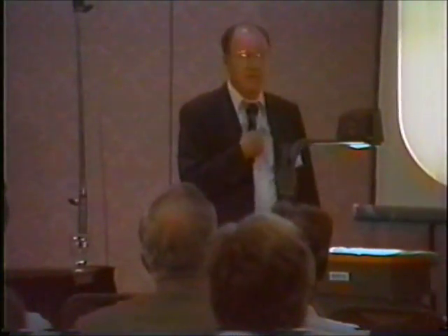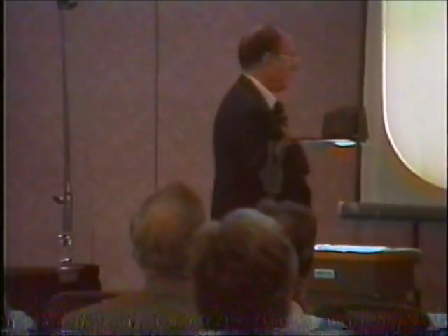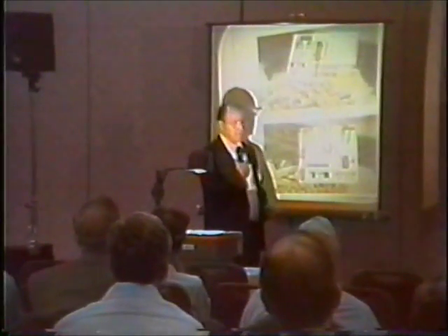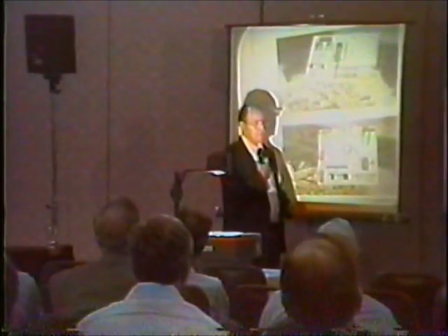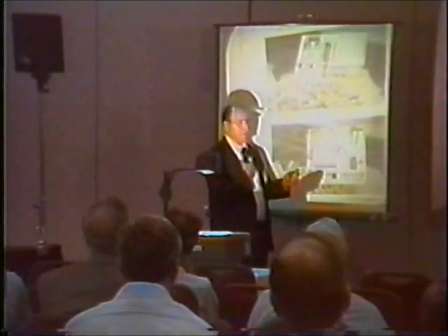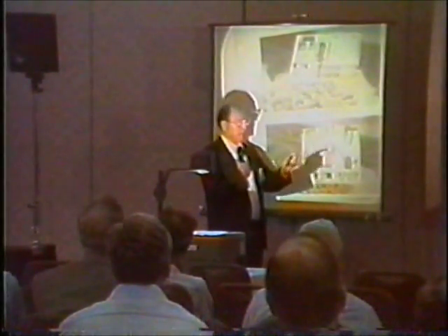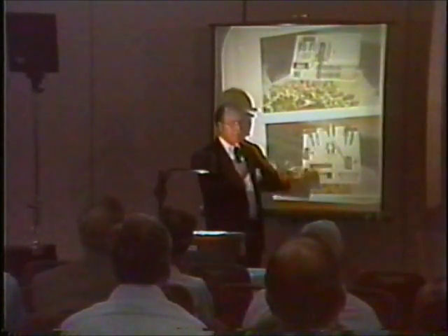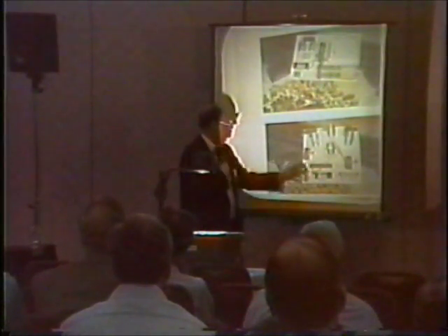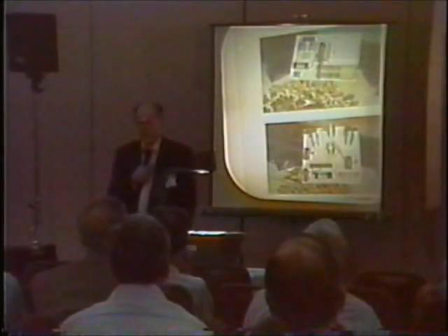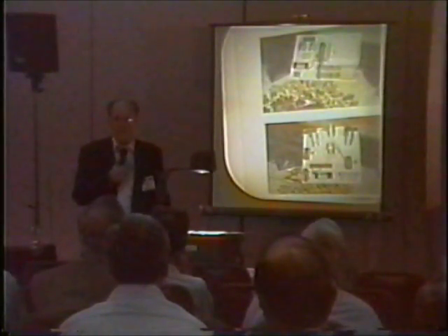And how you know when they're tuned or actually functioning: there's a little neon light that has one leg with a resistor, about a 47,000 ohm resistor on it, on one leg of the wire on this neon bulb, and then there's another leg that just sticks out like an antenna. When this thing is functioning properly, that bulb lights up. So you know immediately when it is.